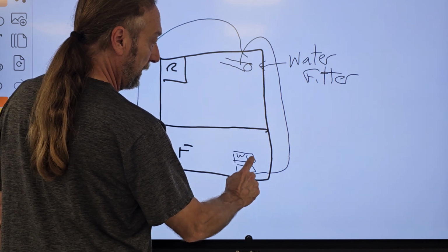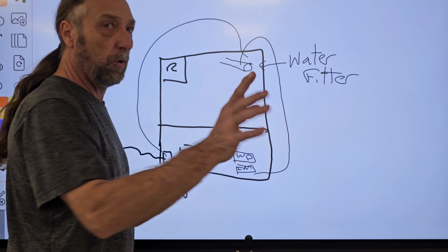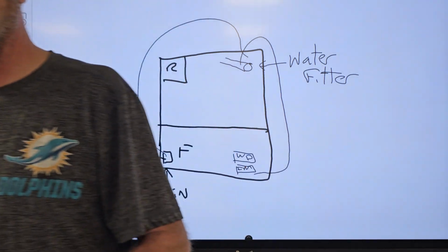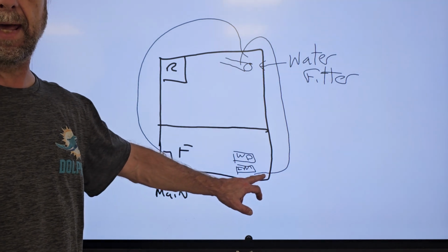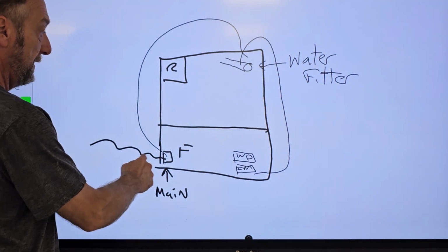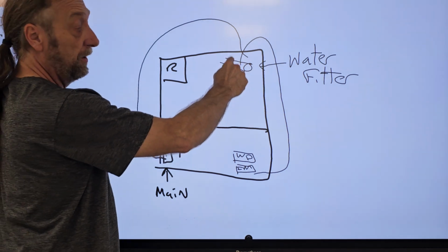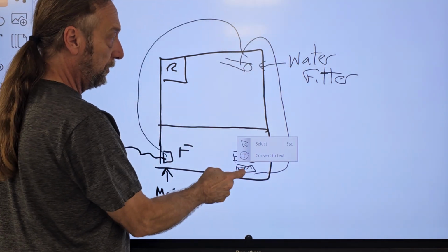Water on the door, and I would just put WD, and then the flex tray ice maker. I'm not even going to go over the Crescent one. So it comes back down to this water valve, and if I want water on the door, this one sends water to the filter. The filter comes back down here. Water on the door goes where? Where does that piece go?